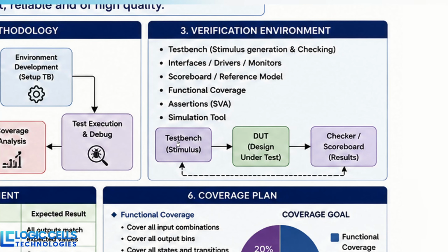How will you be generating the data? Manually, will you provide A equal to 0, B equal to 1? No. So there will be a standard test bench stimulus generator. This is your stimulus generator. That will give the information that it generates to the DUT. If your DUT is following some protocol, depending on the protocol, you need to provide the data from the test bench. Then this DUT does its functionality. It will give you the sum if it is an adder. There is a checker or scoreboard. This will give you the result that your test case is pass or fail.